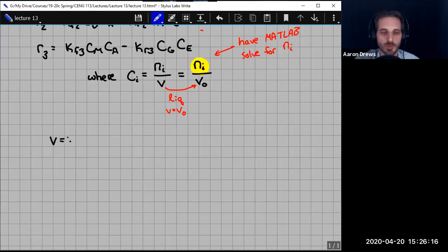So the inlet volumetric flow rate for the soybean oil, we know we're providing it at 1 kilogram per minute. And if we looked up the density of the soybean oil, we would see that it was 1 liter for every 0.930 kilograms.